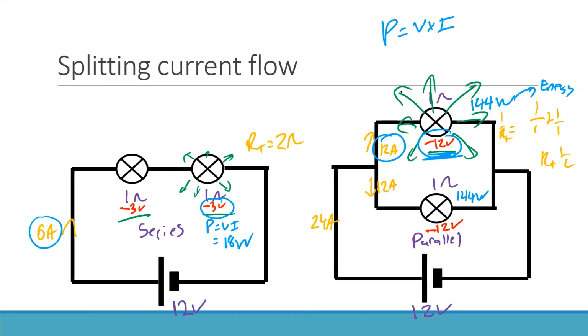But the reason I'm showing you guys the other information about current is because I always used to get really confused. I used to be like, won't these ones have more current, and so won't that balance it out? Actually it doesn't, because there are two splitting things. There's two ways to split this circuit. There are more available paths for the current to go through. So the current is larger. Look at that. The current is 24 amps compared to this one, which is 6 amps. And not only is the current greater, but it's also dropping more voltage. So that means we end up dropping more power.